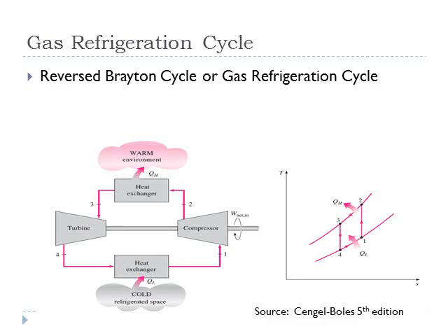Since the refrigerant at state 2 is having high temperature, higher than its immediate environment, in the heat exchanger the heat, because of temperature difference, is lost to the environment and the refrigerant gets cooled. We can see this cooling process of the refrigerant inside this heat exchanger from 2 to 3 process, represented on TS diagram as well, and we see QH amount of heat is rejected, and as a result the temperature will decline from T2 to T3.